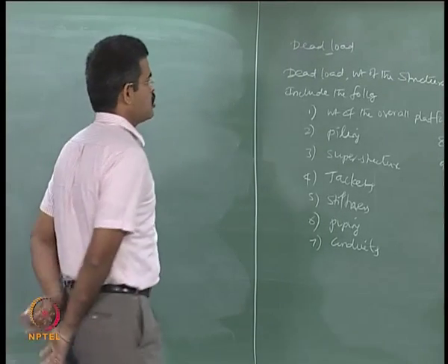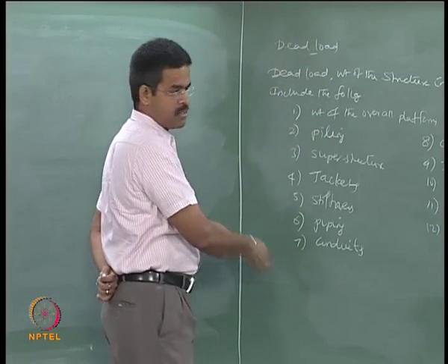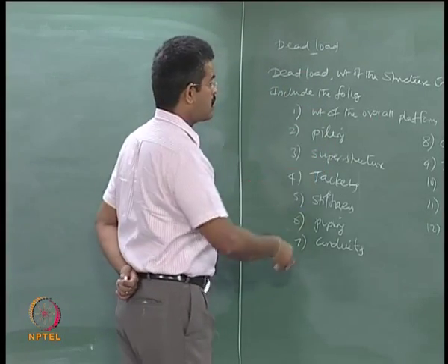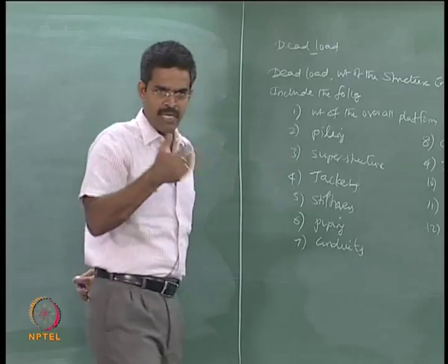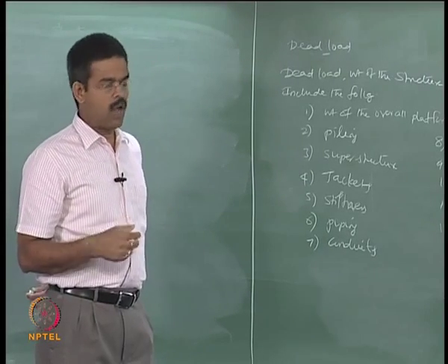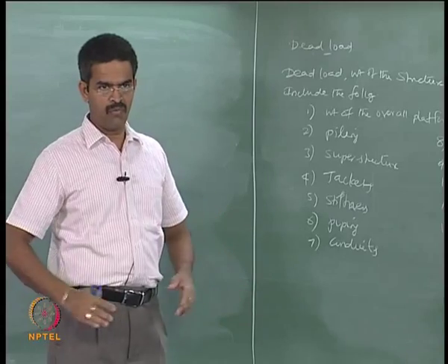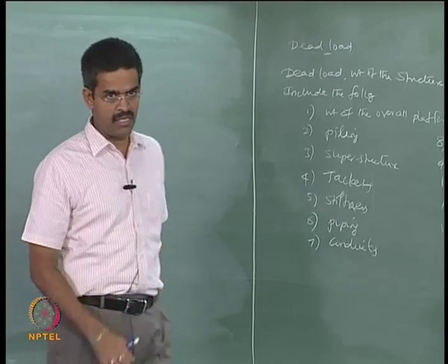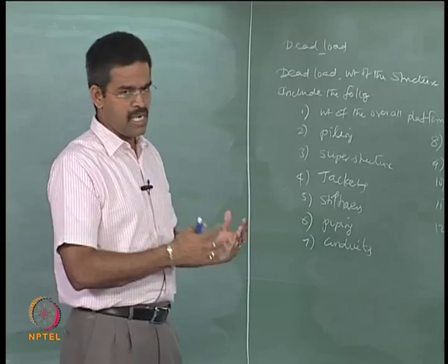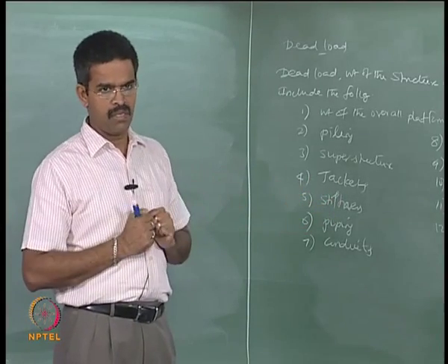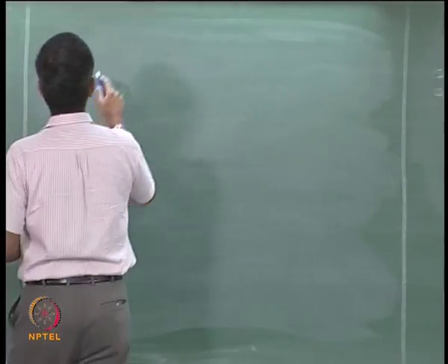So, if you are not clear about the sources of the loads, where they are coming from, which are included, which are excluded, and what are the intensity values, an approximate idea, okay, how much live load or dead load I must consider on a deck platform of 90 meter by 90 meter, I must have an idea, otherwise you will never really understand the problem in a physical meaning. Okay.